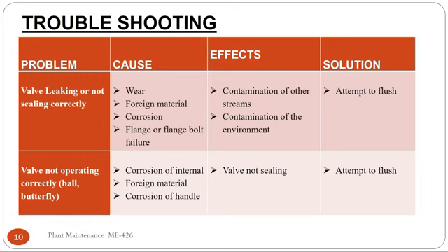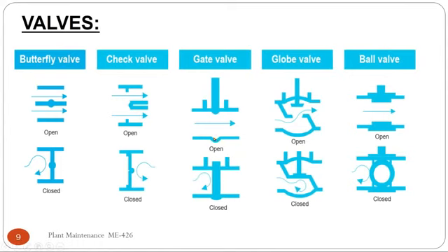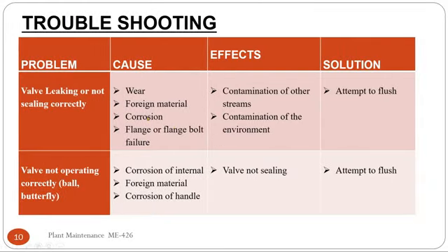So in the last picture you can see, if the foreign material is stuck here, how will the gate valve disc seal properly? So the gate valve will be stuck in this position, then there is leakage, or maybe due to corrosion, maybe due to several reasons.